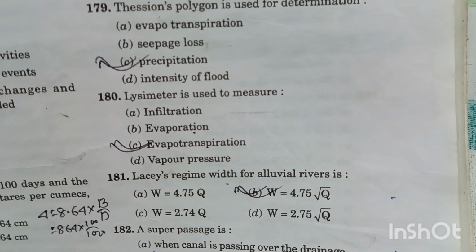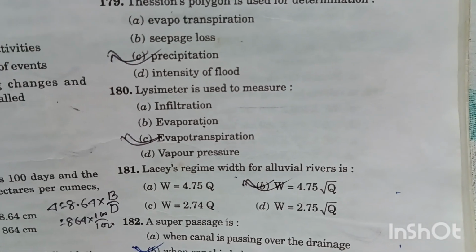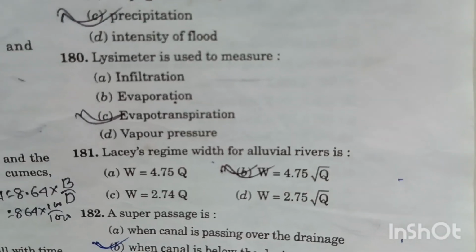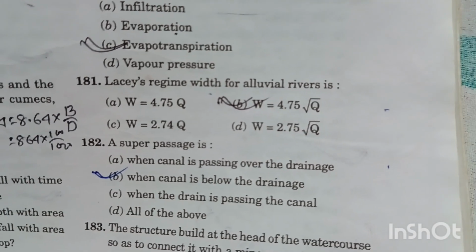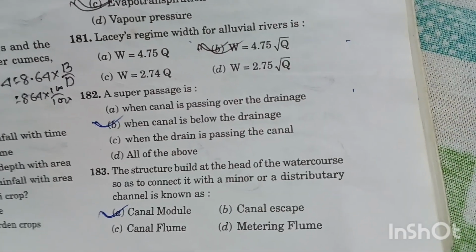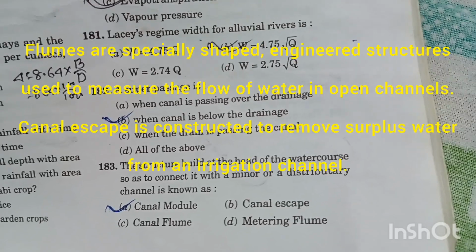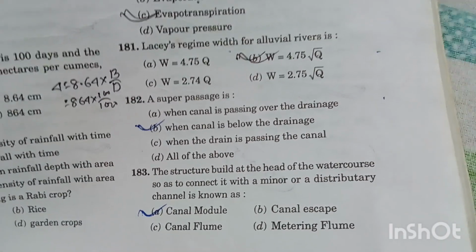Question number 181. Lacey's regime width for an alluvial river is W equal to 4.75 root over Q, where Q is the discharge of the river. Question number 182. A super passage is when the canal is below the drainage. Option B is the right answer. Question number 183. The structure built at the head of the water course so as to connect it with a minor or distributary channel is known as canal module. Option A is the right answer.